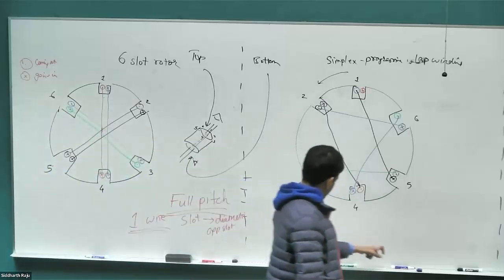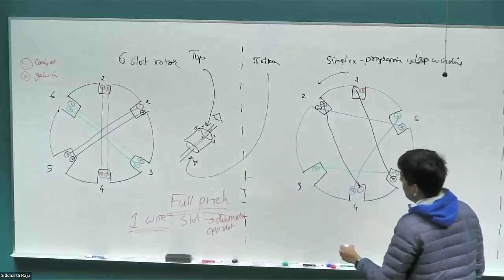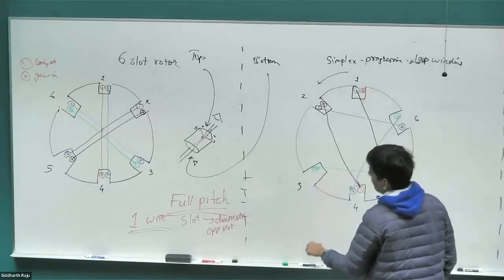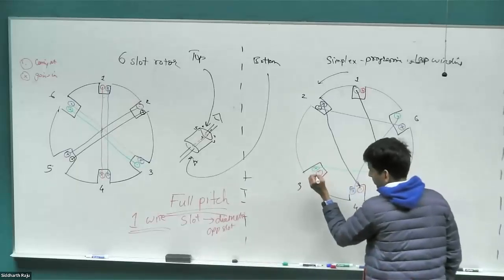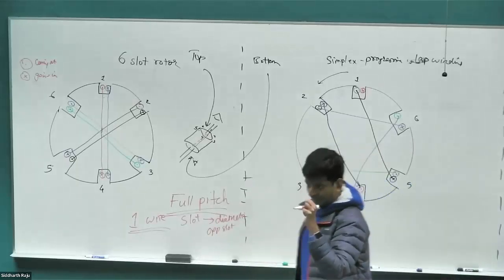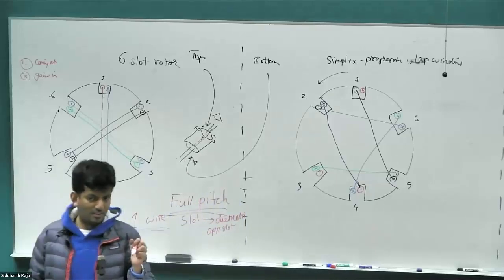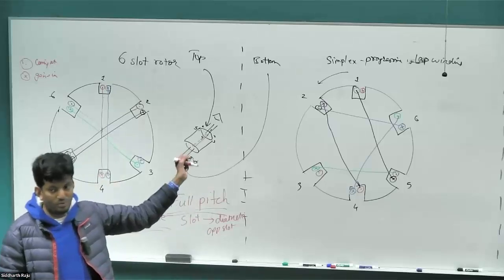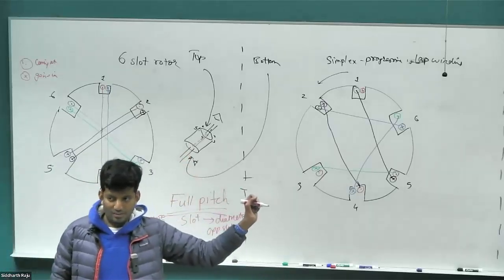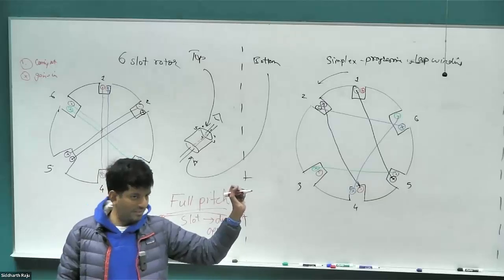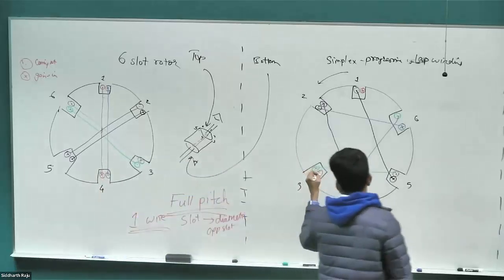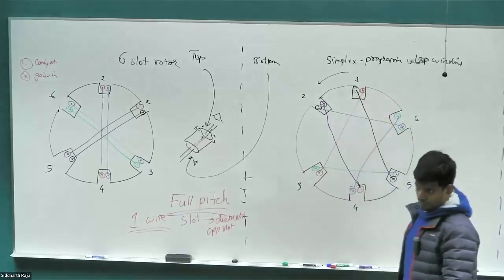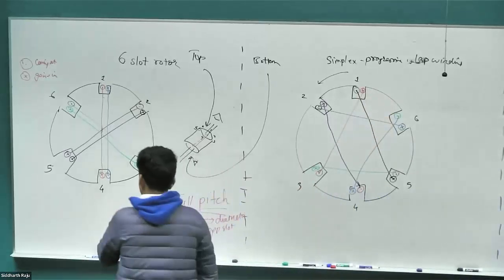Now something interesting happens. We have 3. The direction will go from 3 to the commutator. I haven't drawn the commutator. All of those conductors need to go to the commutator, right? But is there a 1? Keep following the rule. That's it. We have closed a full loop. It's a single wire.